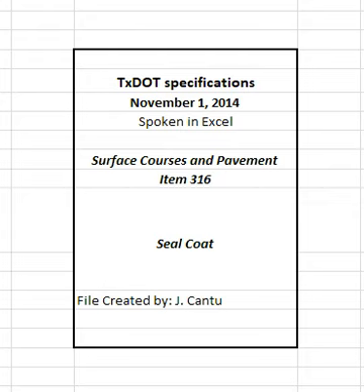4.8.2 Limitations. Do not apply asphalt to the roadway until traffic control methods and devices are in place as shown on the plans or as directed. The loaded aggregate spreader is in position and ready to begin. Haul trucks are loaded with enough aggregate to cover the shot area and are in place behind the spreader box, and rollers are in place behind the haul trucks.